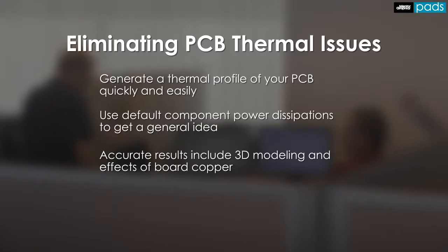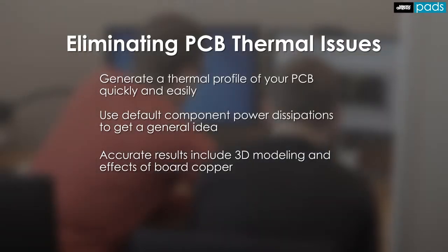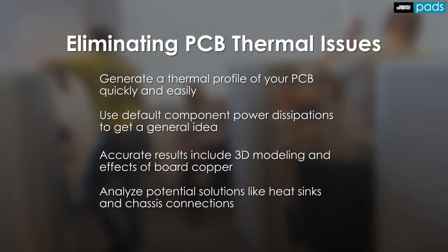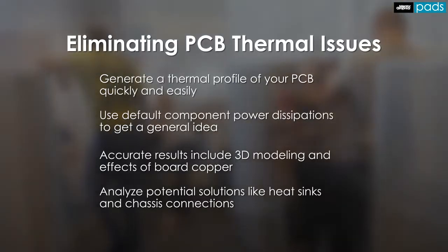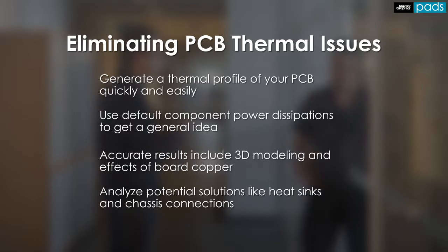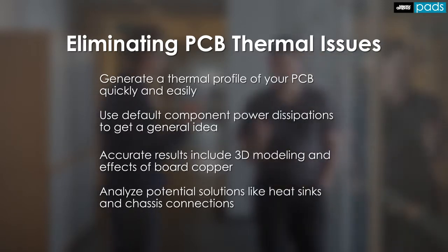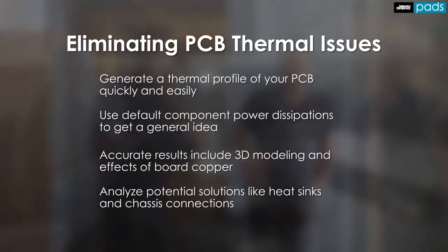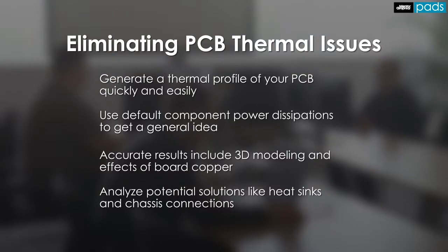All simulations use 3D models including the component height, so that the effects of airflow through the board get properly modelled. You can analyse potential solutions to thermal issues by adding heatsinks, screws or wedge locks that connect the board to the thermal chassis, or airflow changes, to name but a few. So let's take a look at thermal analysis and how to address thermal issues through simulation.